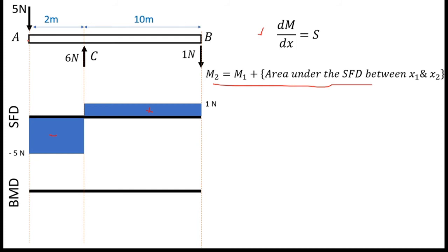At the starting point you can see it marked as A. If we consider supports, this is a pin support and this is a roller support, right? This point A is a free end. Free end means there are no restrictions, so the bending moment value at point A is 0. So now I know this bending moment diagram will start at this point with 0. At the ending point you can see a roller support.